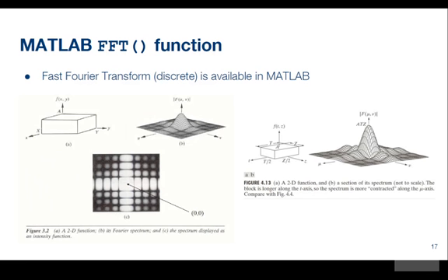This fast Fourier transform is available in MATLAB. I should probably be a bit careful. I've called it FFT, but when we're doing 2-dimensional fast Fourier transforms, we need to use FFT2. I probably should change that. Okay, there is a function for images, which is FFT2.